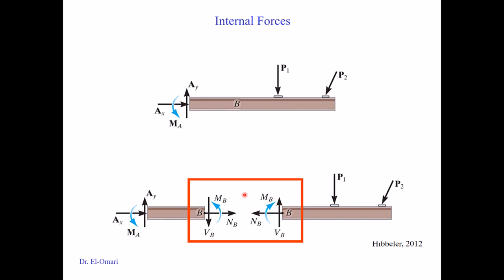Please be careful about the difference between cutting through the member and taking it apart at a pin. A pin has no moments, so it has only the pin reaction. Some would draw a moment by mistake when they take it apart at a pin. And this is totally different because we're talking about pin reactions. Here we talk about internal reactions or internal forces: shear, normal, and moment.